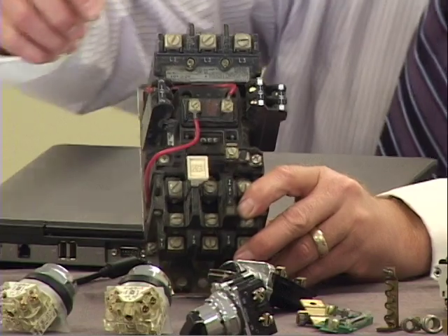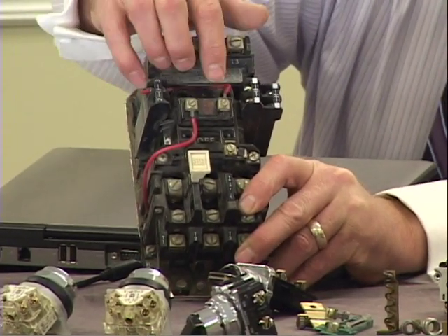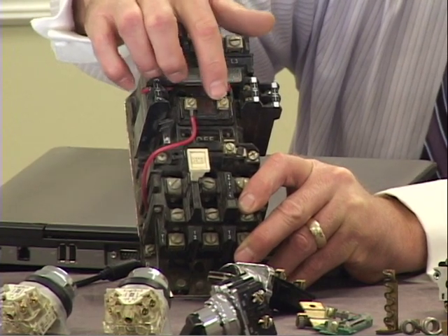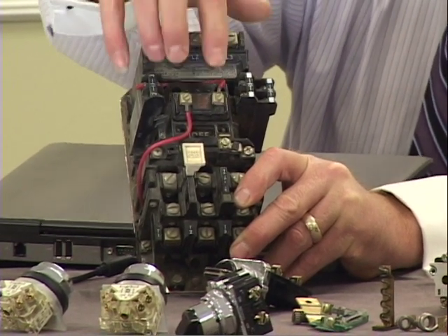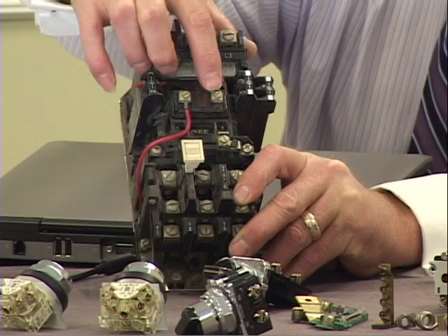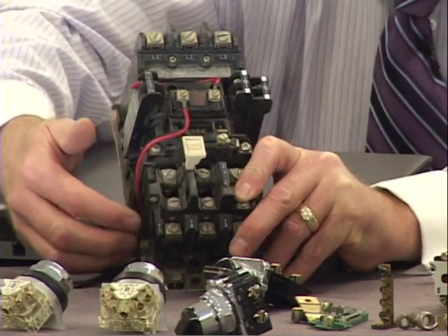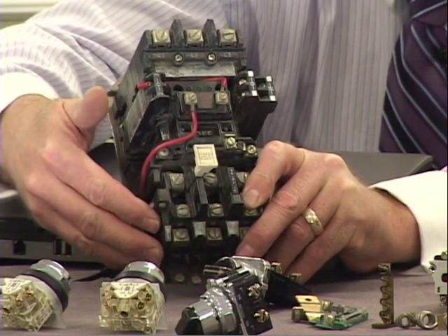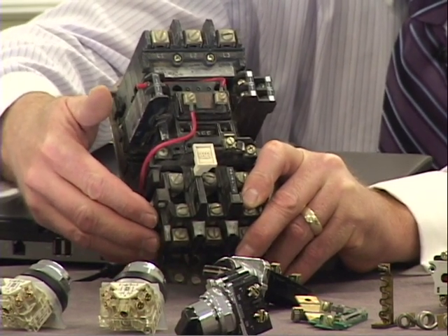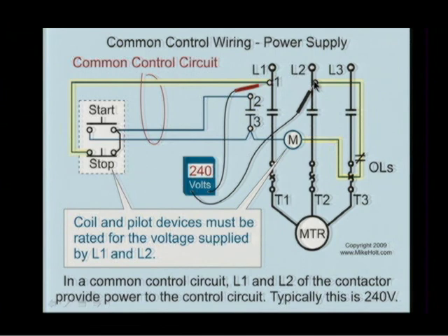Dennis, what have you got there? Well, I was just going to mention that a lot of times you're going to see that your manufacturer is going to have a lot of the material that you're covering or the wires that you're talking about there already pre-wired. So you're coming off of your contactor, you're coming down, and you actually go down to your overload contact down here. All right, let me show you what I got here on the screen, and then you show me physically where it goes. You ready for this? We'll do one step at a time.